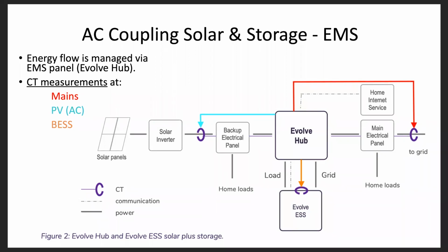As per your wiring picture, you show the solar being tied into the sub panel with power outage. Will the solar inverter remain on, or is it shutting down in backup? Great question, and that's why the solar inverter is integrated with the backup loads panel, because the battery goes from being synchronized to the grid voltage to serving those backup loads as a voltage source when the grid is down. That same voltage source becomes your new synchronizing voltage for the solar inverter.